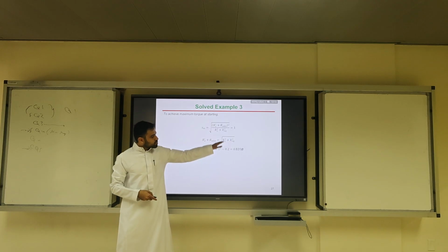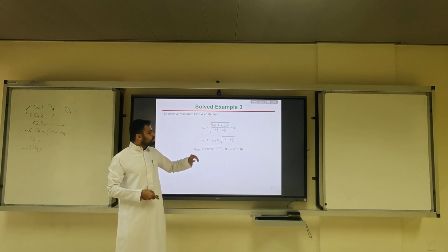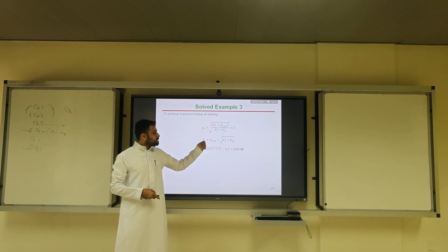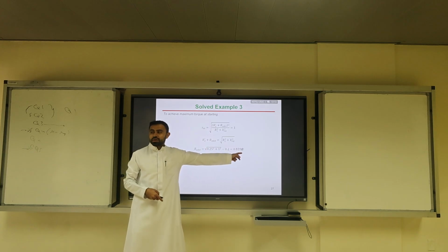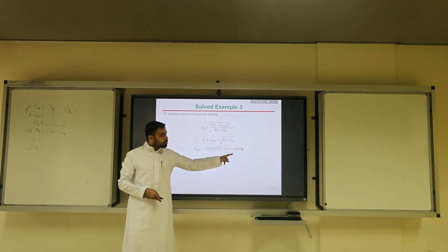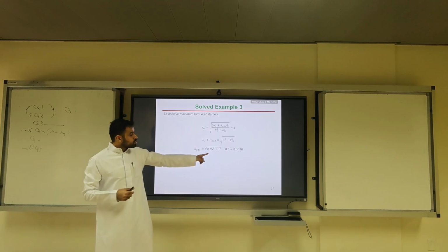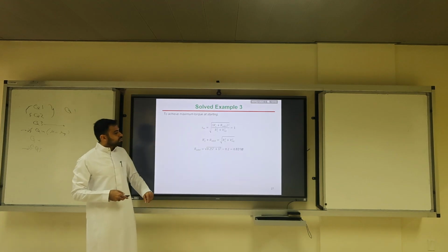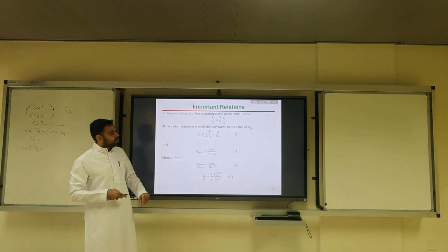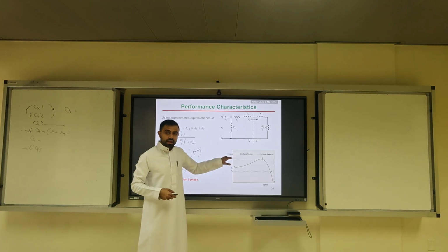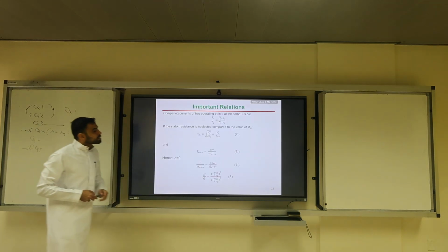So the R1 squared plus X equivalent squared, square both sides, and subtract. This is a number, you can calculate it. Minus the 0.2, you should get 0.831. So if you add 0.831 to the wound rotor after the slip rings, you should be shifting the torque to be at the start. So the maximum torque will be here at the beginning. Okay?